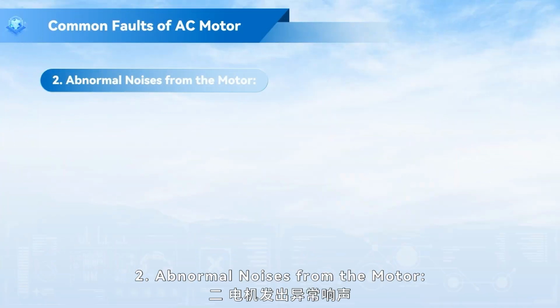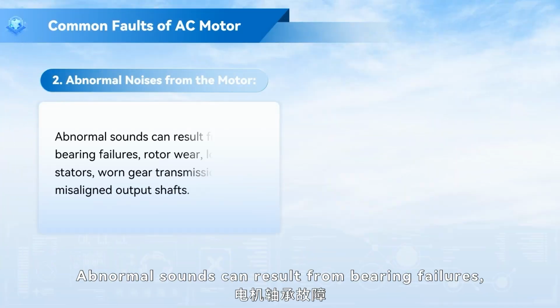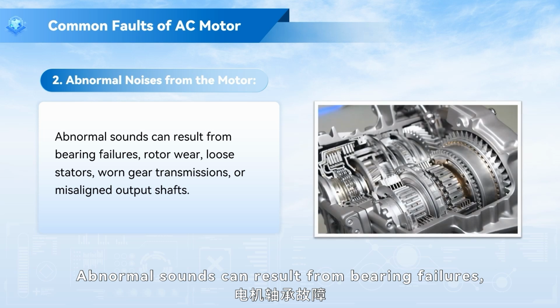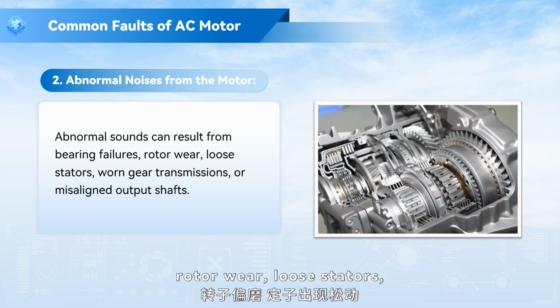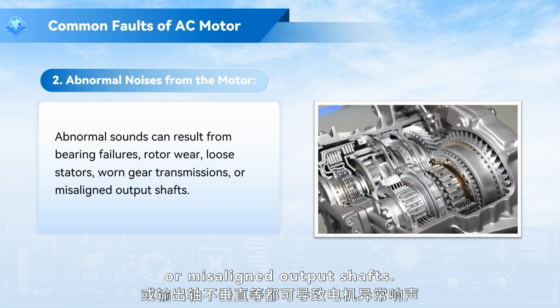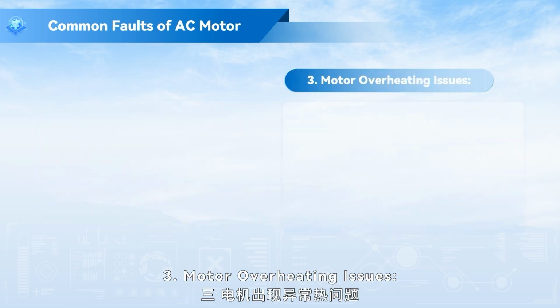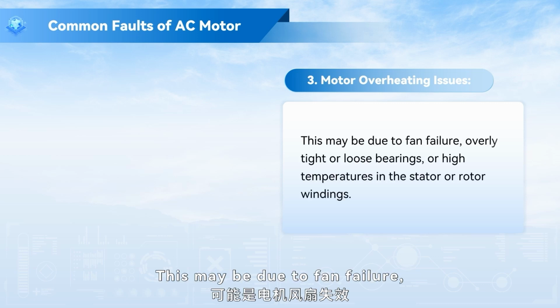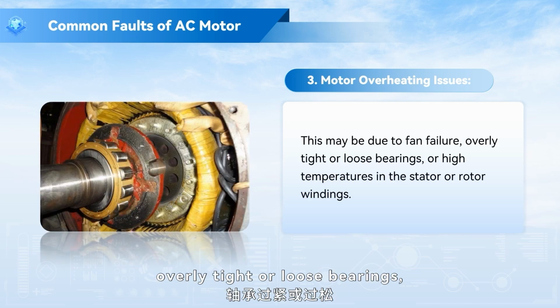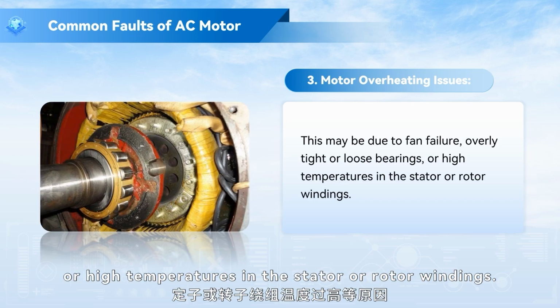2. Abnormal noises from the motor. Abnormal sounds can result from bearing failures, rotor wear, loose stators, worn gear transmissions, or misaligned output shafts. 3. Motor overheating issues. This may be due to fan failure, overly tight or loose bearings, or high temperatures in the stator or rotor windings.